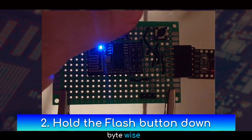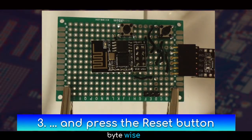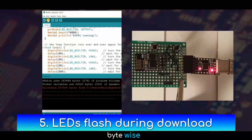Putting the board into flash mode requires holding down the flash button whilst pressing the reset button. The flash button needs to remain pressed for a couple of seconds as the module reboots. Flash mode allows us to download the program. The download is started by clicking on the download button in the toolbar of the Arduino IDE. In some versions, it's necessary to reset the board again after download.